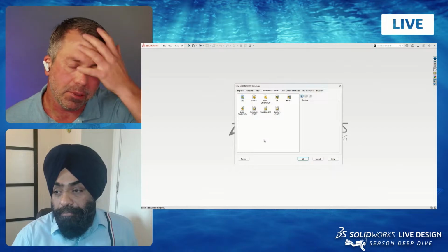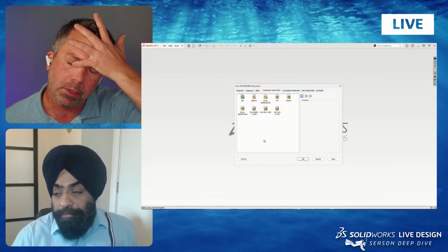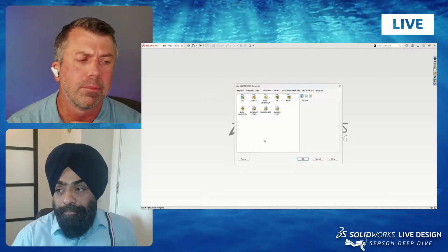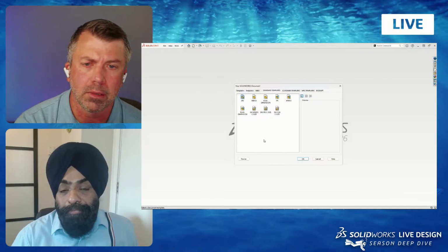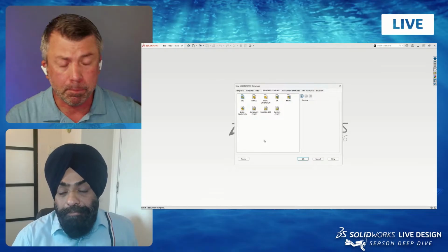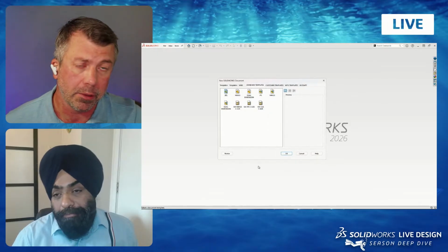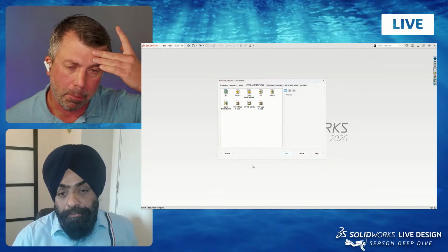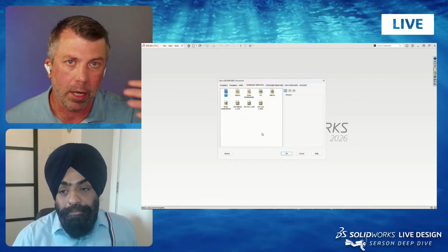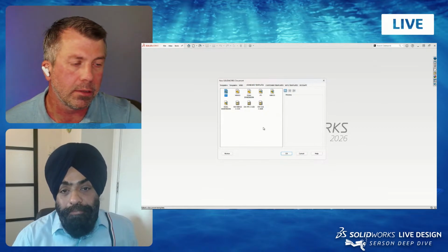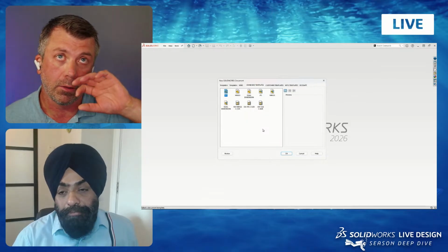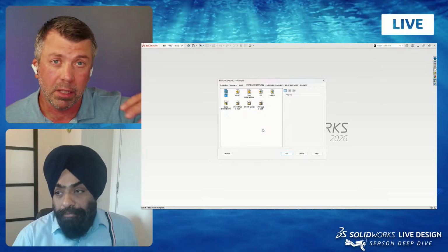Because what happens when you use that Boolean subtraction, it takes away your master wing body that just disappears and leaves you. So I don't think so, but Deepak, if you think of something, just let me know on LinkedIn. I know we're connected there, or shoot me an email. That's just the way I've always done. When you do, like, I did a paddleboard design, and figuring out those ribs, it's always been just the copy body approach, and then subtracting those extra bodies away as you go through the features. You could probably connect them if you did this. If you connected all the ribs together so they're one solid body, then you could do it in one go.